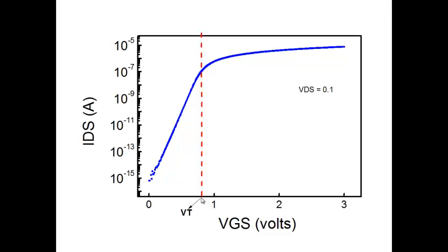But note, if this slope is constant, which we will see in a minute, as you shift VT towards this, your off-state current goes up. This is a major problem in current technology. You've gone towards very short channel length transistors, you want to operate at very low supply voltage, and therefore you want to make threshold voltage small. And as you make threshold voltage small, the off-state current becomes very high.